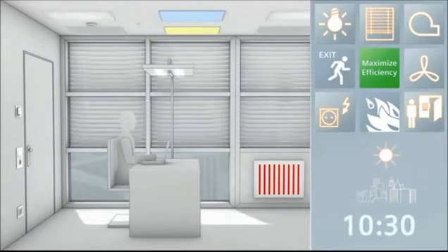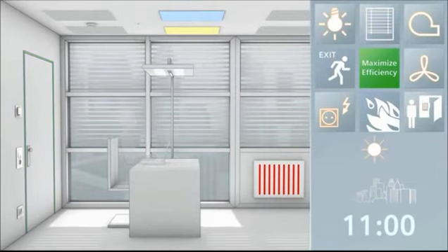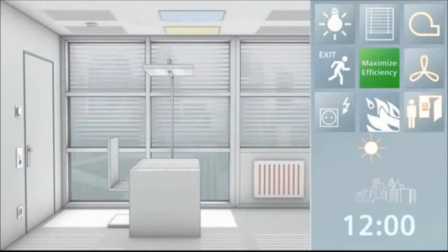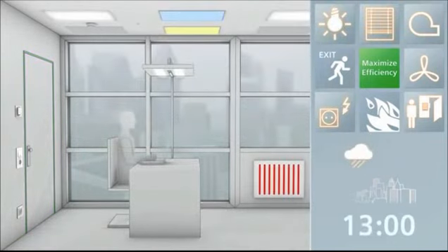Depending on the work and weather situation, the room automation system adjusts the lighting and climate automatically over the course of the day. On hot days, the window blinds are closed and the air conditioning is switched on automatically. During the midday break, all functions switch back to standby mode. This reduces power consumption. After the midday break, all functions switch back on and regulate as required. For example, if the sky is cloudy, the window blinds are opened and the lighting adjusted.